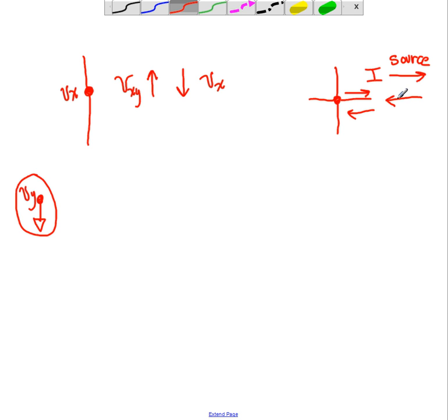If the current is going into that point, we say that point is acting as a sink for current. So when we talk about a point, we can talk about the voltage level at that point, which can go up or down. We can also talk about the current coming out of that point, or the current going into that point. This will become very important when we talk about the limitations of particular devices, components, and modules in our design.